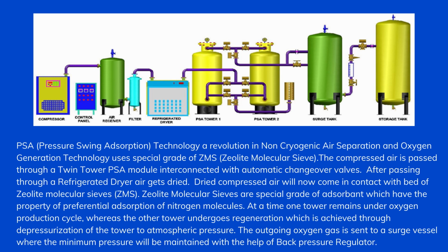Dried compressed air will now come in contact with a bed of zeolite molecular sieves, ZMS. Zeolite molecular sieves are a special grade of adsorbent which have the property of preferential adsorption of nitrogen molecules.